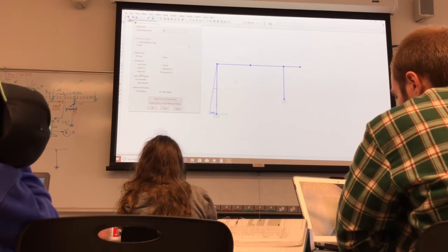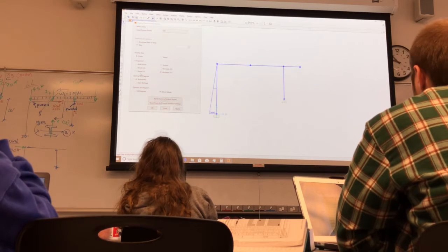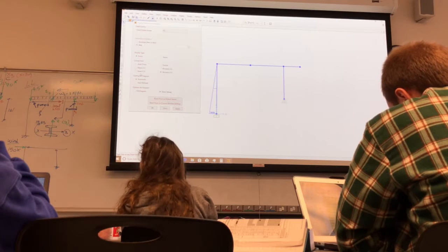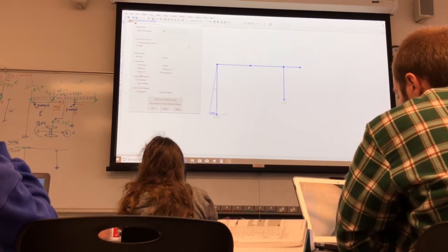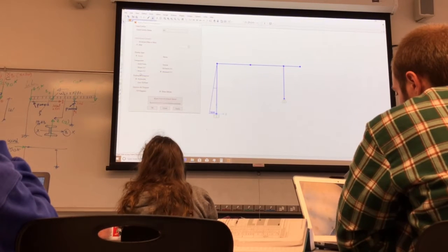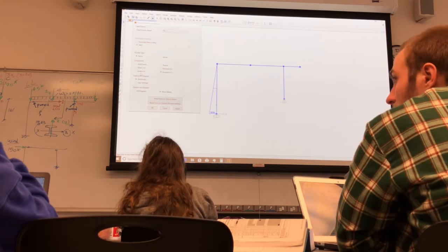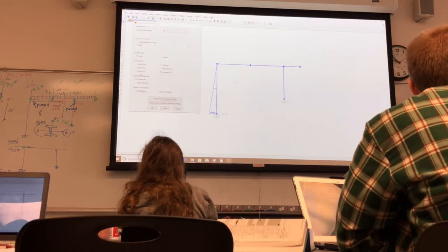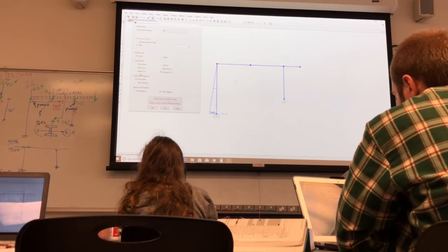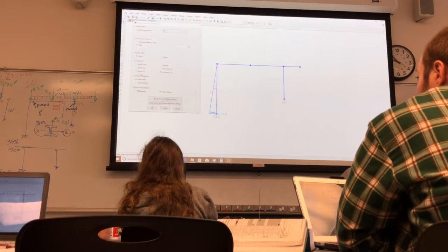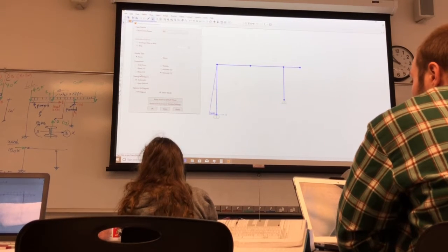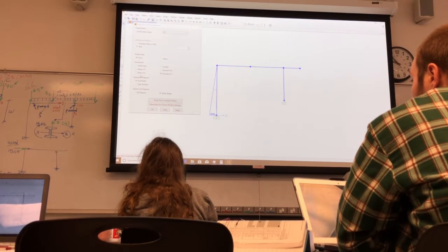So now we need to do the load combinations. We need to know how to do load combinations and put that in Excel, or find what to design for. So these are the loads on the structure we see: dead, live, snow, wind, and earthquake. So let's assume we're trying to design this element right here. We're interested in this column. Let's see what force I should design for.